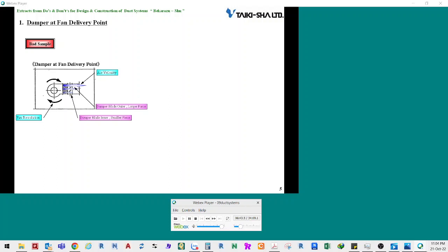If the shape of the ducts does not fall within conditions which I will explain next, the ducts will become too resistant. Fans may not send the required airflow, and the ducts may vibrate. As a result, ducts and fans may break. Fans must therefore be designed assuming the shape of the ducts to be used.